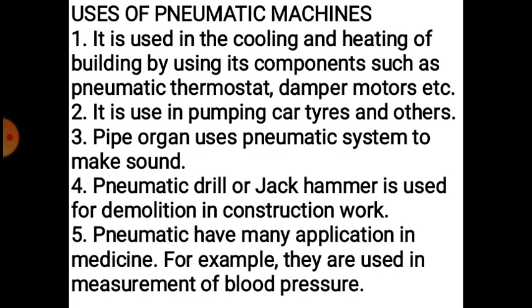Air is collected from the atmosphere, is taken through an air filter, and air compressor raises it to a required pressure. The temperature increases as the pressure increases, and it is passed through an air cooler with air treatment to remove moisture. This treated pressurized air is stored to maintain the pressure. A pressure switch is fixed to the storage reservoir to start or to stop the electric motor when the pressure falls and reaches the required level, respectively.